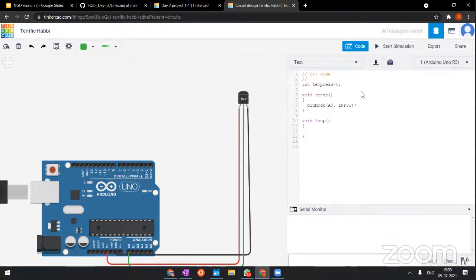So this is basically just like an output screen in any programming language, and so I'll just show you how to use this. So in the void setup, we need to tell Arduino that we're going to be using the serial monitor as well in this program. So for that, the code is Serial dot begin.